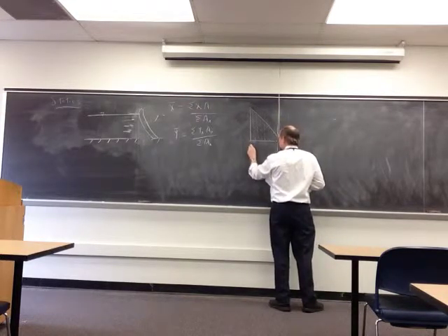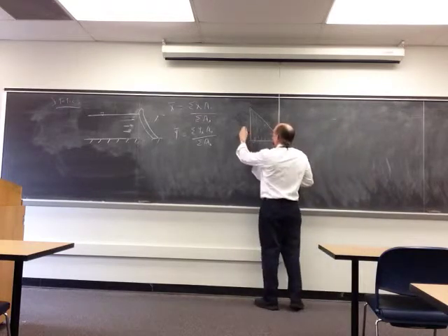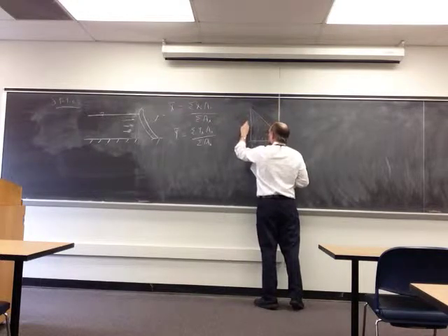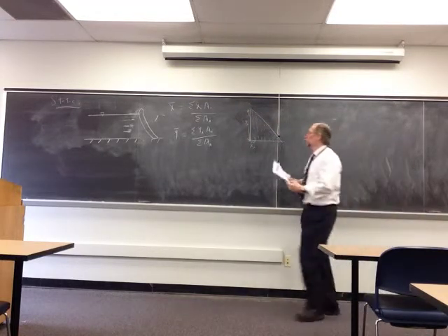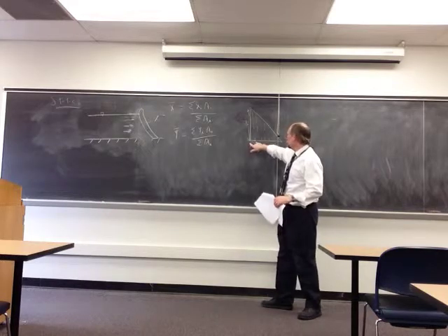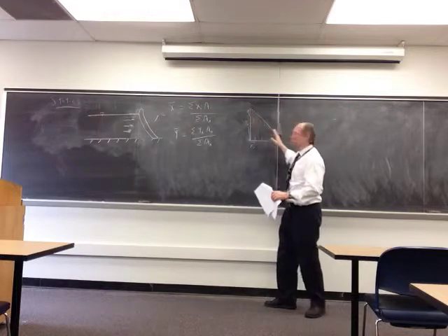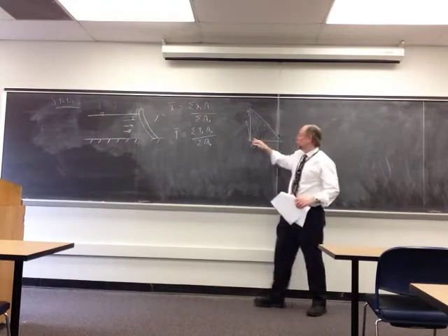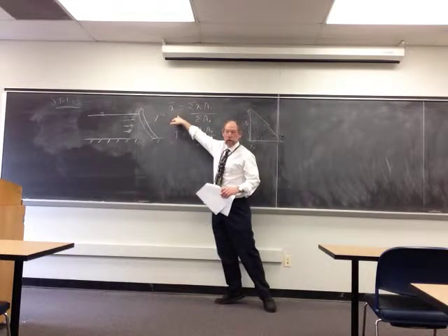Each rectangle is xi wide, yi tall, and xi times yi is the area. So for each rectangle, you take xi times its area, sum all of those up, and then divide by the sum of all the areas. And you get the x component of the centroid.